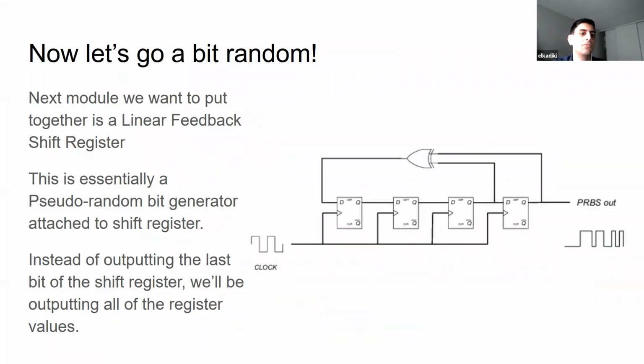Now we're going to get a bit random. This one's a new addition. It's kind of a fun little thing to put in, and you might have some fun with this. I found this really interesting. You might have heard this in your C courses or other courses that computers really don't have the ability to do things randomly to an extent. You have a pseudo-random bit sequence that you can almost predict if you had enough of them. The idea of a pseudo-random bit sequence is it's repeatable. It'll overflow back and continue to be random, and it won't ever enter a dead state.